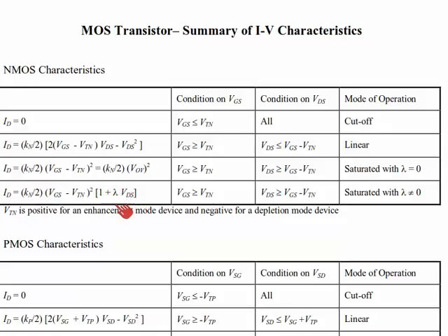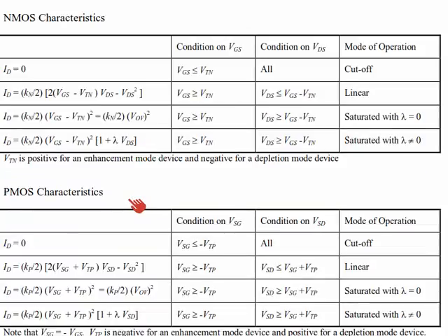So if you need to include channel length modulation with this parameter lambda, by the way, lambda, L-A-M-B-D-A, is a PSpice parameter that you can use for circuit simulation, you can, using this multiplication factor. We typically won't include it in hand calculations, but every once in a while it comes in handy. Well, there's an introduction to the current-voltage characteristics of the transistors, the MOS transistor.